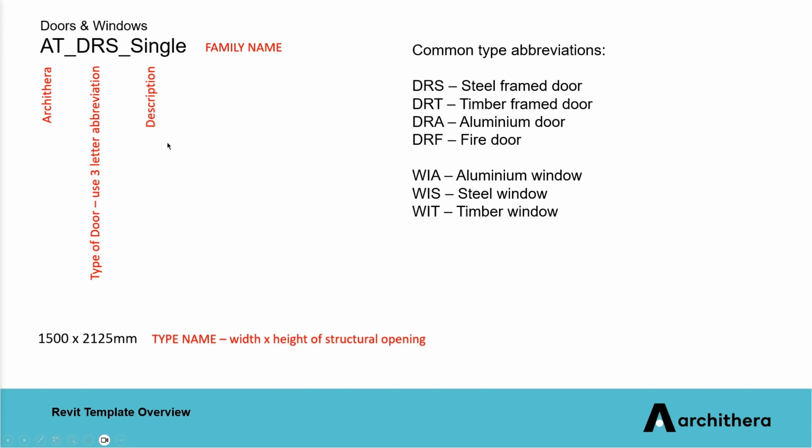So this is going to be all placed in your family name, and then the type name in the family. So if you create a new type, it's going to read as the width. So first of all, it's going to be the width times the height, and then it reads neatly, so you know all your families are also grouped neatly, and if you read a family name, it starts off with the width and then your height value.